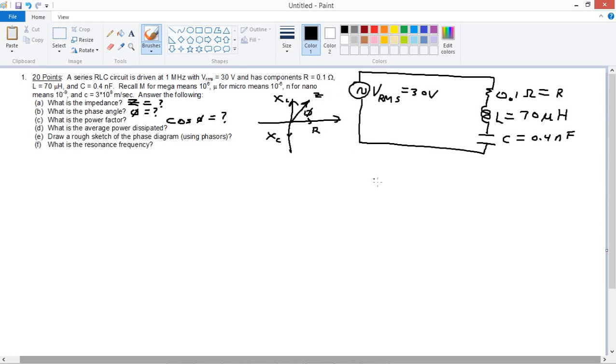This is the phase angle. Remember, this phasor diagram is telling you where the current is compared to voltage. So voltage times current times the cosine of the phase angle tells you the projection of the current in the same direction as the voltage.